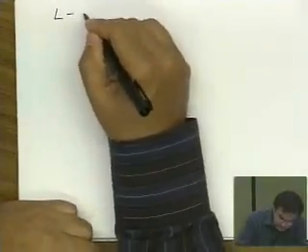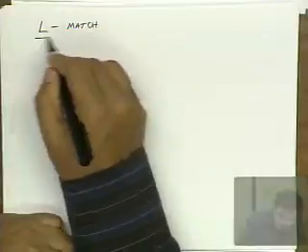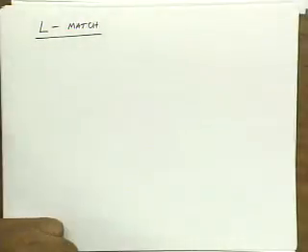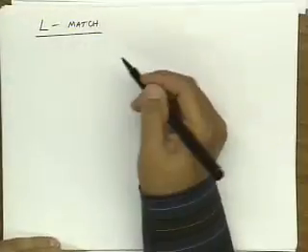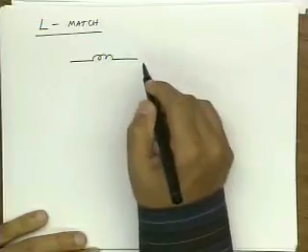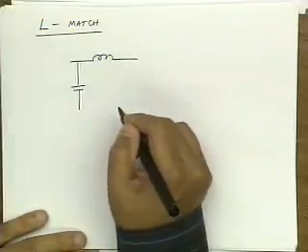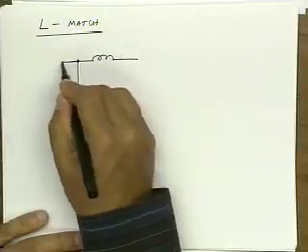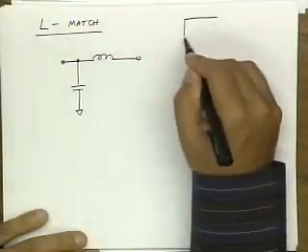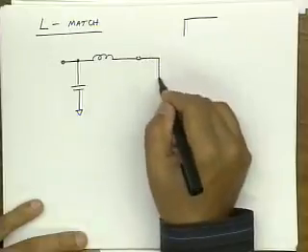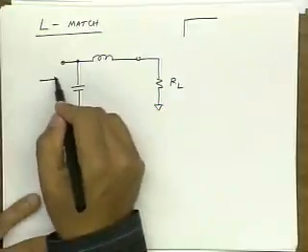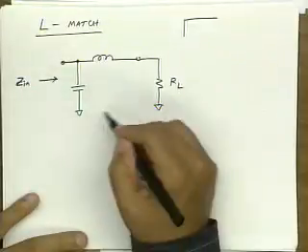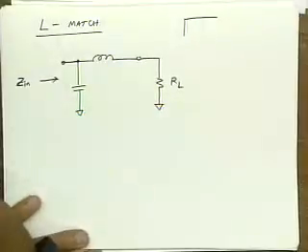All right, so what we're going to do is focus on some other impedance matching networks. First one we'll look at is called an L matching network. Okay? And the idea behind an L matching network is as follows. So first, let's see how it works. Let's just look at a particular example. It's called an L matching network because it looks like an L, right? There's our L. And what I'm going to do is hook up an RL here, and then I'm going to look at Zin to see what happens at resonance in this circuit.